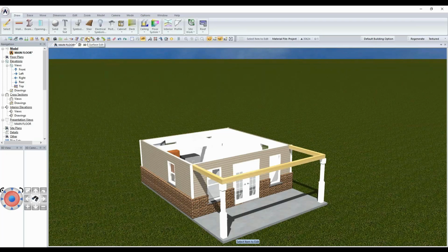And if I wanted to make all these beams white to match what the posts look like, there's also a tool in here called Edit Surface Copy Paste. So you click on a surface that you already know, and then you click on the other one. So if your corner boards are the wrong color, I can click on the siding and I can click on corner boards and they'll update. It's not really something I want to do though. I want them to stay white.